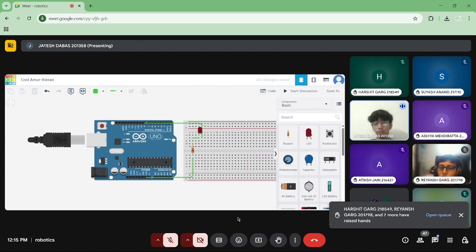So when we're coding an Arduino, we need to know which component. There are multiple types of components in robotics, in electronics. So there are actuators, which are motors, right? And there are sensors, which would be infrared sensors, ultraviolet sensors, moisture sensors. There are a lot of sensors. So when we're using sensors, we use analog pins, which are input pins, right? And when we're using digital pins, Adit explained it to you that they are just for on and off. So we mostly use motors or LEDs for digital, right? Okay.